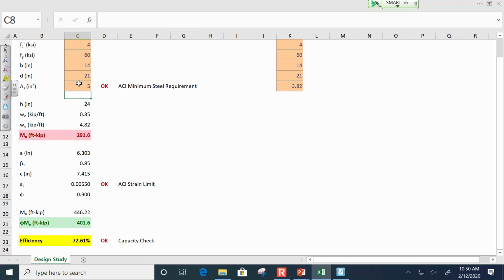Now, what you probably can't do is say, well, this floor has 80 PSF. No, it can only have 60. Because then you're starting to tell the architect, you can't use this for an office building. It can only be a hospital. I'm designing an office building. It's got to be an office building. So the loads are the loads. That's like the concept, that's what the building's being used for. Does that make sense? Any questions?